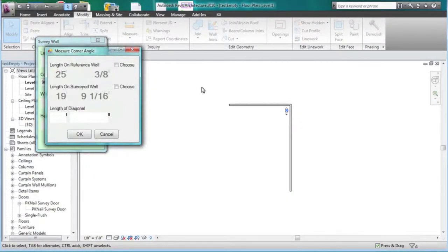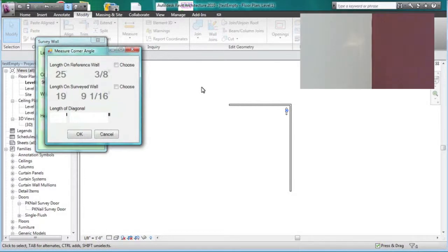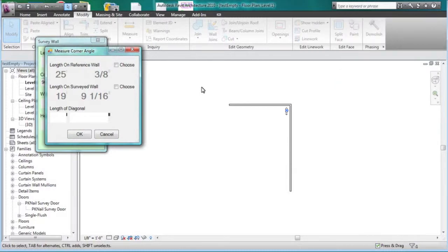So here we are scanning the wall to get the correct measurement, and the disto comes across to get the maximum length. So we received a measurement of 24 feet 3.5 inches. Due to a limitation of the disto when using the maximum and minimum function, we have to enter it manually, so I'm doing it here.